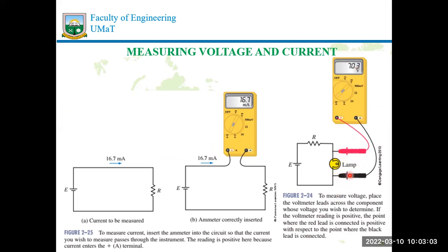to measure the voltage across. So if I need to measure the voltage across this very particular resistor I have here, the voltmeter should have its terminals connected across R. When it comes to current, current is normally a case where you have to break the circuit and connect the ammeter in series with the network. In series with the network. So let's kindly take note of that.